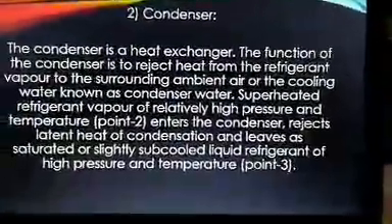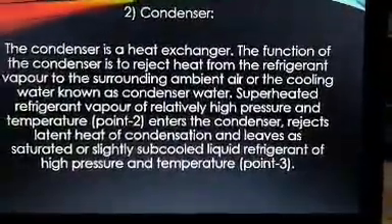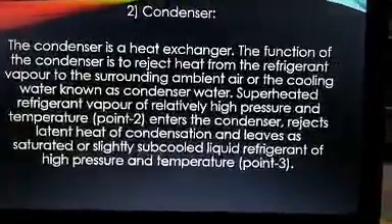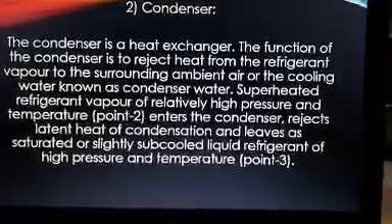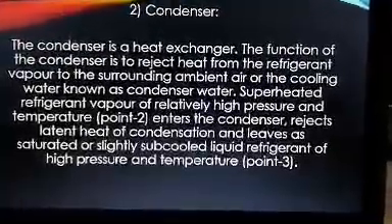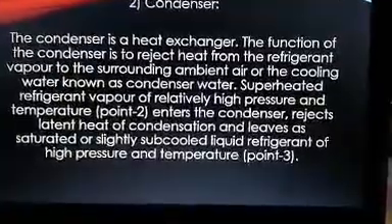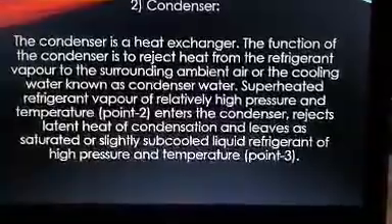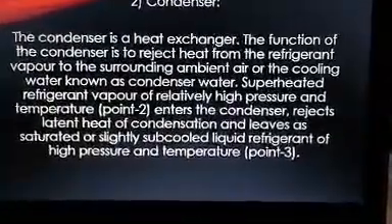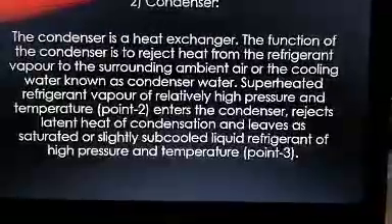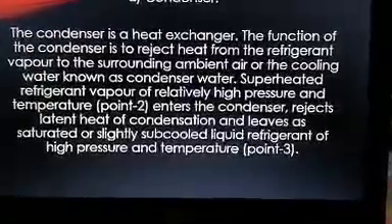Condenser. The condenser is a heat exchanger. The function of the condenser is to reject heat from the refrigerant vapor to the surrounding ambient air or the cooling water known as condenser water. Superheated refrigerant vapor of relatively high pressure and temperature, point 2, enters the condenser, rejects latent heat of condensation and leaves as saturated or slightly subcooled liquid refrigerant of high pressure and temperature, point 3.